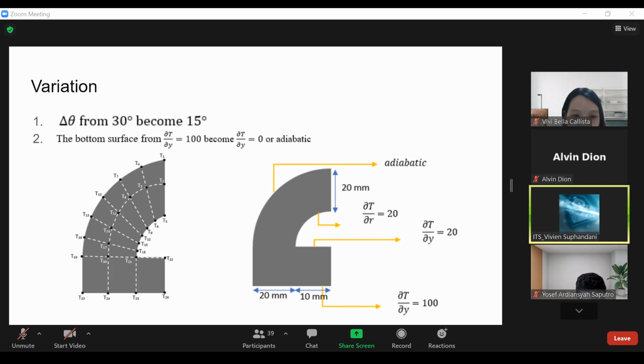But sometimes using all Neumann boundary conditions will make the calculation almost singular. So it will be easier if you can combine with a Dirichlet boundary condition. If you use all Neumann boundary conditions, that will sometimes be a problem with the solution. It depends on the coefficient matrix that has been constructed from this case.